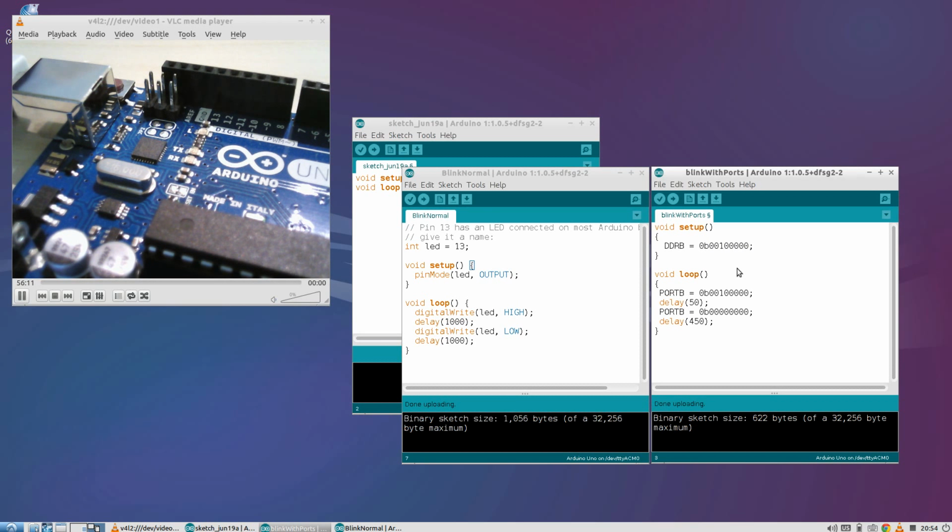In computer science, we start counting at 0. So this is pin 0, and then to the left is pin 7. That's a group of 8 pins. So 0, 1, 2, 3, 4, 5, that's going to be an output basically. If I look over at the schematic of the Arduino, which I didn't pull up, so you've got to trust me on this one, the LED pin, which you talk to at a high level as pin 13, actually maps over to port B5. And so what we've done is we've made it an output here.